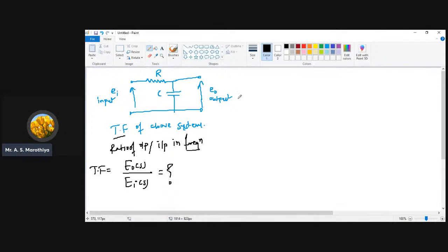Second approach is that directly you can convert this particular network into the corresponding frequency domain. And how to convert that? Again, you need to apply the applications of the transfer function. Like the same circuit I can draw like this. So here we are going to have a resistor followed by a capacitor, but in order to convert the system from time domain to frequency domain, the resistor will remain unchanged. Because resistor is a frequency independent component, it is going to remain R. But here instead of writing C, now we need to write 1 upon Cs. This is very important.